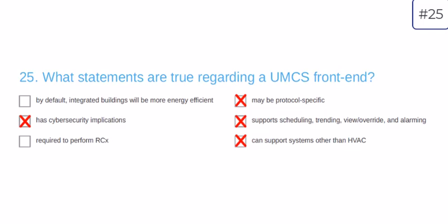That's where we come in. Two, having a front end certainly may ease the retrocommissioning process, but it is not required to perform any RCX tasks. We can supplement with data loggers. We can monitor the system without getting into the logic or looking at the schedules. There's a lot we can infer, a lot we can assess for.